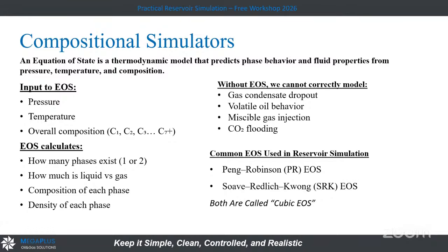So what is the equation of state? It's a function, or equation, that you can go and look for, but I can help you: the two most popular are the Peng-Robinson equation and the Soave-Redlich-Kwong equation, the SRK equation of state, called the cubic equations of state.